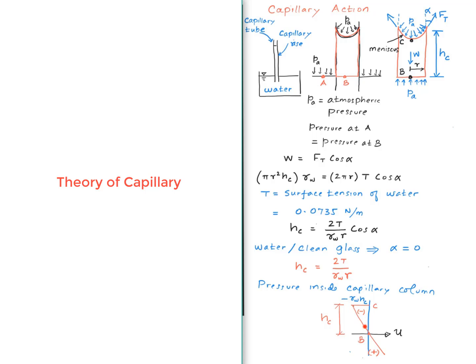And this is the most important point for us, because now we're going to take these ideas and apply it to real soil, and we're going to find that a portion of the soil is going to be under negative water pressure.